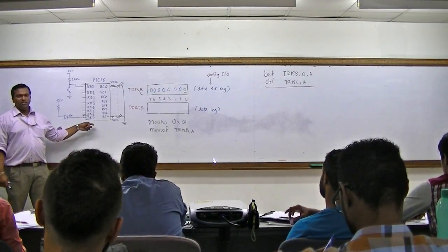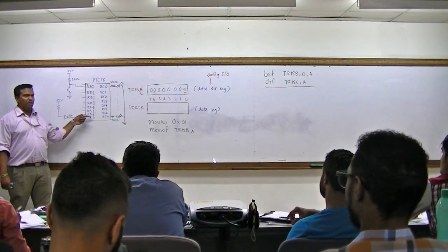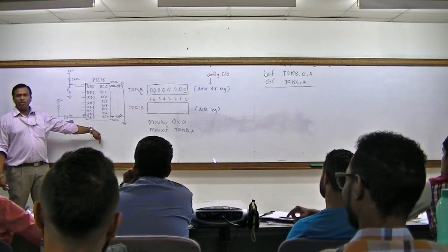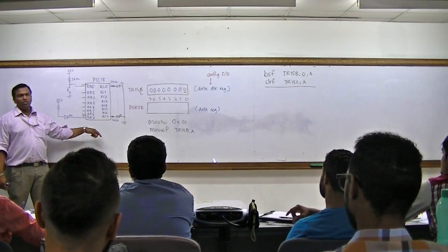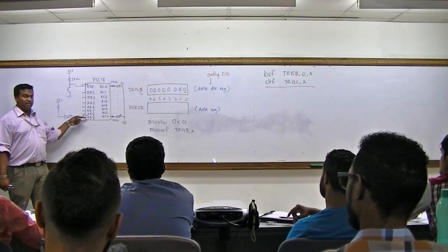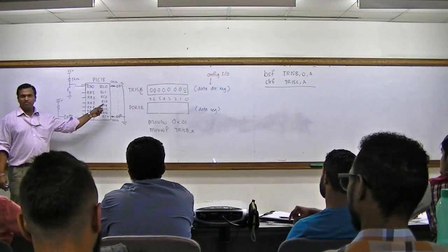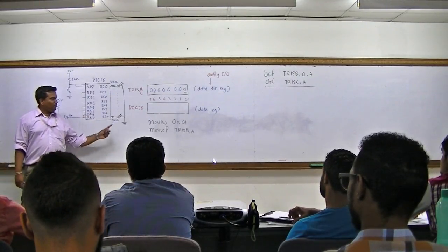But this is much better. When you do this, is the microcontroller using any energy? No. It is just allowing the current to pass through, go to ground. If you want to come up with a design which is more energy saving, you should do something like this. Most of the hardware boards have it like this, not like that. Exams always come like this.